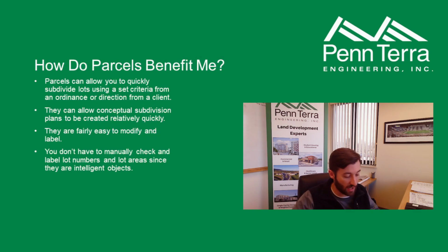So how are parcels a benefit to me? They allow you to quickly subdivide lots using a set criteria. So you'll see a table in a lot of ordinances that give you the criteria you need to use when you create your lots. It's really beneficial in the conceptual stage to come up with something quickly. To come up with more of a final product, you do need to do some more manual manipulation, which we'll talk about in a little bit. But generally, they're fairly simple to modify. The labeling goes pretty quick. You can renumber lots if you need to.